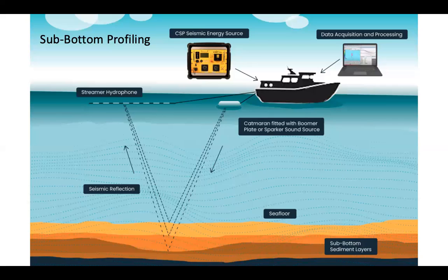Now, the cool thing about sub-bottom profiling is that some of that signal actually penetrates the seafloor and hits layers underneath the seabed, and it bounces off those layers, continues to the surface, and we can hear those in the hydrophone array as well as later reflections coming back. And that allows us to tell something about what's going on underneath the seafloor in these areas, which is really useful information. It can tell you things about where the bedrock is and the rock contact. It can tell you about the sediment structure, old coral growth beneath existing sediments, all sorts of things.